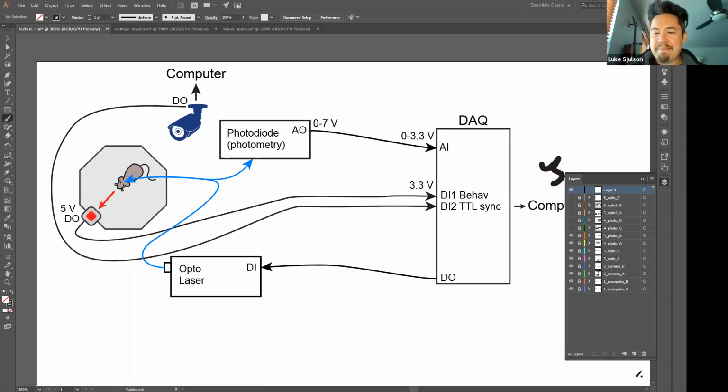So, all right. So the next thing. Yep, the 3-to-1 voltage divider, or 1 to 3, however you want to look at it. Now these things match, and you're not going to damage your analog input. So now we have an analog input, and then we have a 16-bit A to D converter.